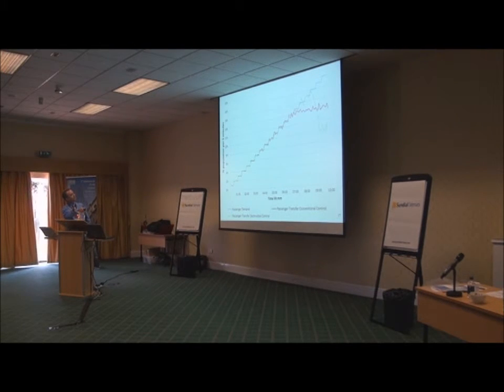We get up to about 18%, and we're still on the line. So it's great, and it is true. If you go into buildings where destination control has been turned on, the day before it was turned on, there was a big queue in the lobby because the conventional system is saturated. The day the destination control was turned on, there was no queue in the lobby. It was clearing, and you actually do get extra handling capacity. It's real, believe me.